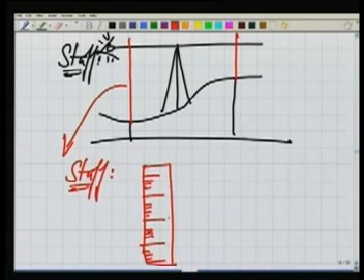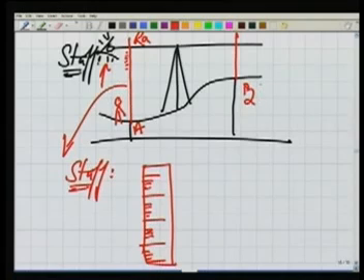We will see the kind of graduations also in those. These are basically vertical scales like this, and someone is holding this vertical scale here so that it is kept vertically, and we have the graduations. So from here, when we are observing, we are taking the reading RA at this point A, and if this is point B, we are also taking the reading against this staff, which is RB.